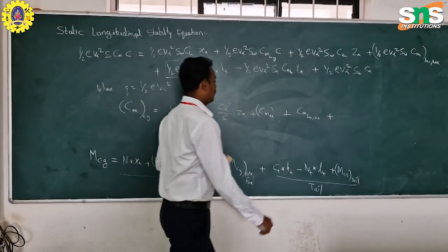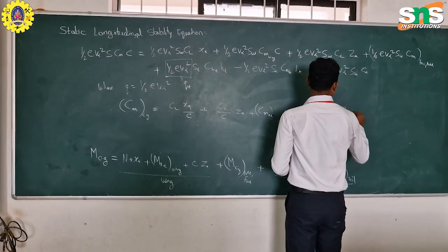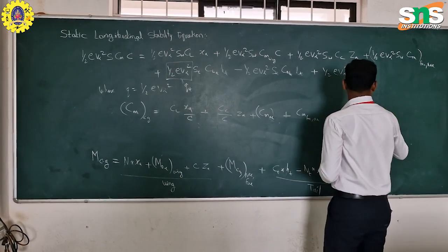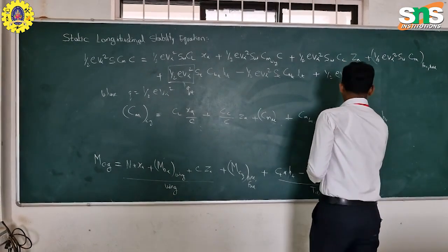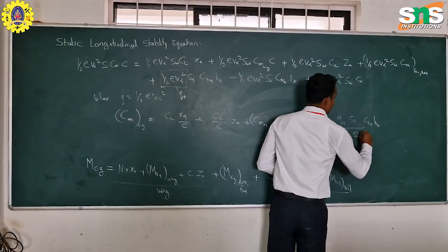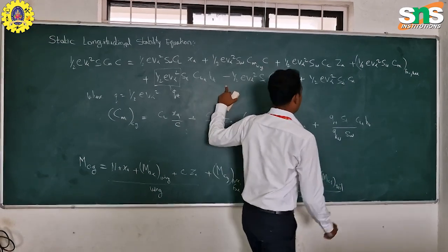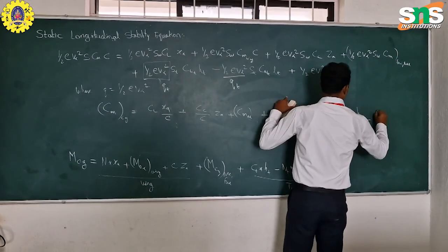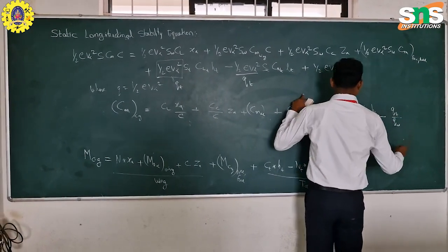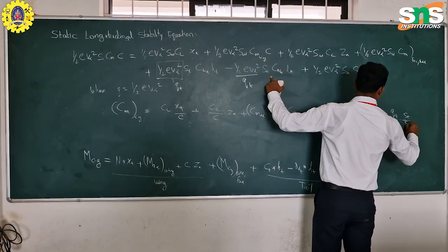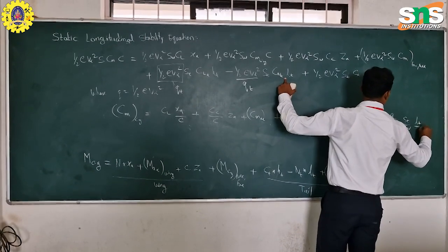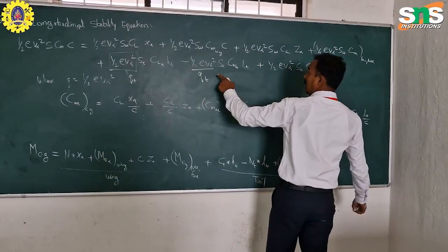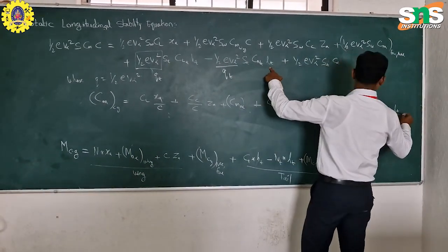So this is S T, right? So we will get Q T by Q T S T C L T, H T divided by Q of wing, S of wing. Right? So this term is over. And again minus, for this, again this entire term is Q T. So tail dynamic pressure by wing dynamic pressure, tail surface divided by wing surface, and the L T by chord. Here also it will become chord, and this becomes dimensionless. And we are getting L T, right?